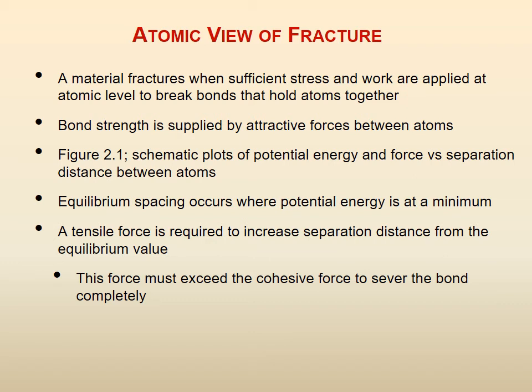What is fracture, right? The material is being deformed until it fractures. So what is a solid? It is atoms, and between atoms there are forces that join them together. We work on it, we apply forces from outside until these atomic bonds, interatomic bonds, are broken, and then fracture will happen. The bond strength is supplied by attractive forces between atoms. We will see on the figure on the next page, we have schematic plots of potential energy and force against the separation distance between atoms. We will see that shortly.